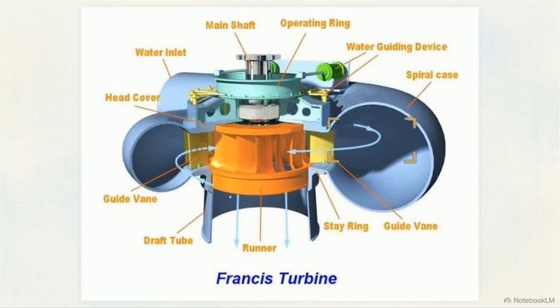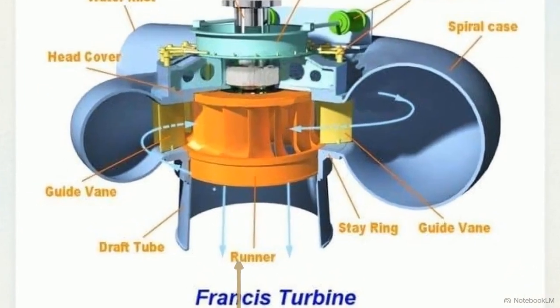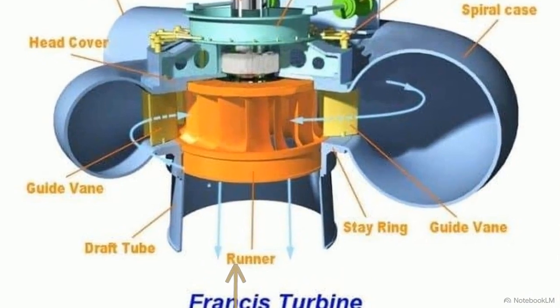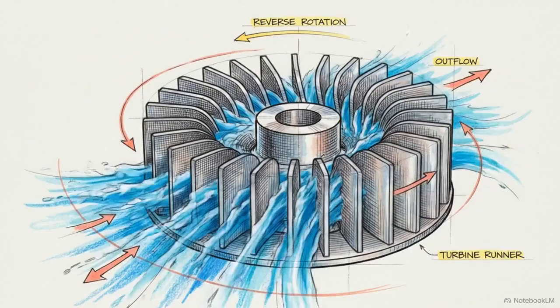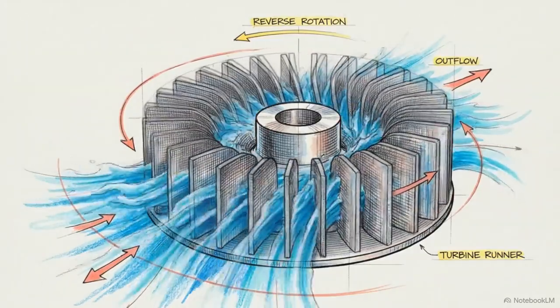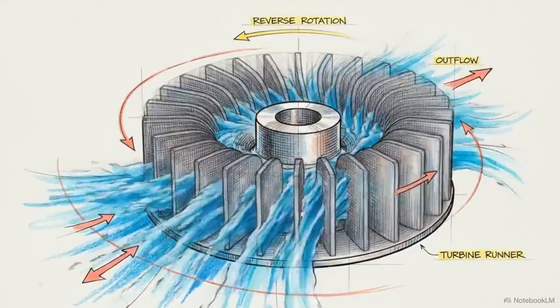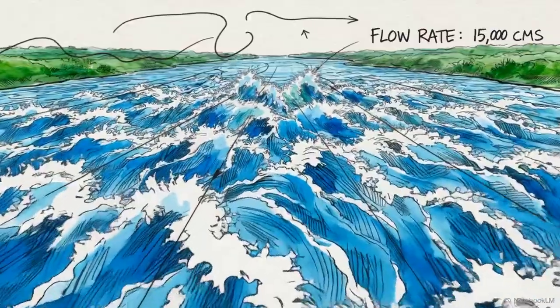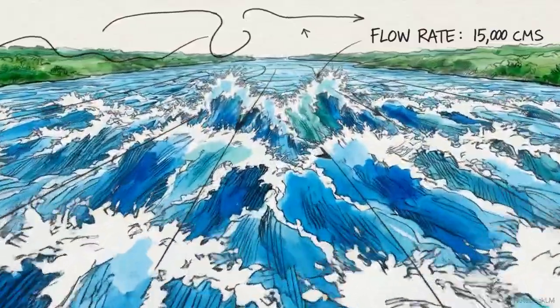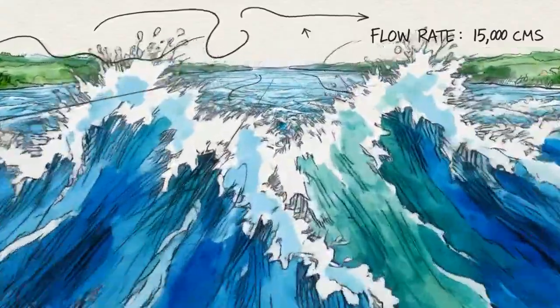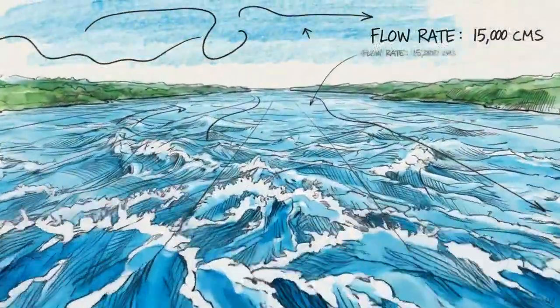As these arrows show, water enters the runner radially from the perimeter and is forced to exit axially down the center. The runner is densely packed, typically using 16 to 24 fixed vanes to handle these medium-pressure environments. The Francis turbine essentially functions like a centrifugal pump running in reverse, making it a standard choice for most major dams. Different challenges arise in low-head geographies, where water drops only about 50 meters, but features massive, fast-moving flow rates.